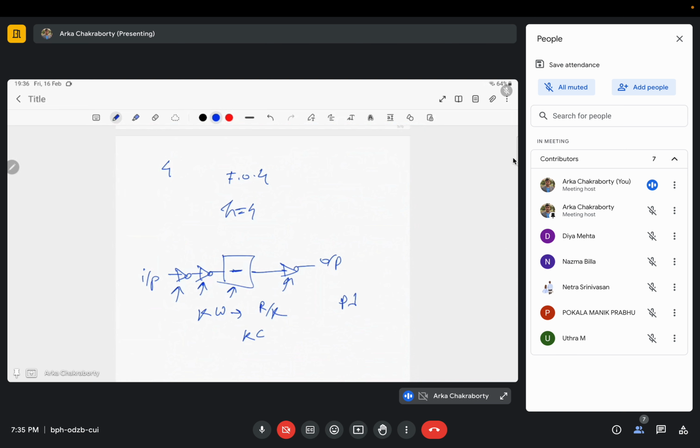So my net propagation delay, sorry, net parasitic delay will not be affected, but G and H are going to change the load capacitance terms. So how much work is needed to be done for getting the optimum delay, that is the least amount of delay? If you solve it using I equals C dV/dt, and if you do this calculation,